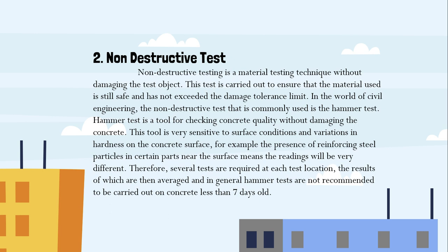For example, the presence of reinforcing steel in certain parts near the surface means the reading will be very different. Therefore, several tests are required at each test location. In general, hammer tests are not recommended to be carried out on concrete less than 7 days old.